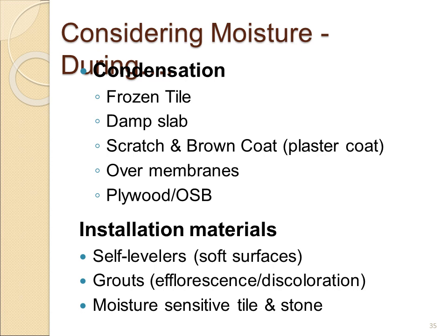When we consider moisture or condensation of materials within the assembly, it's another consideration. One thing we've run into quite a bit is frozen tile, especially cement-made tiles, or natural stone that's stored outside and brought in the night before, but because they're on a pallet, the internal boxes are still very, very cold.